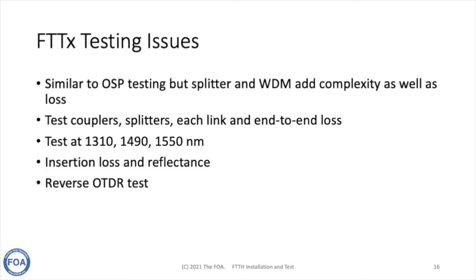The tests that will be done will be tests to measure end-to-end insertion loss during installation and before operation, with tests done at both 1310 and 1490 nanometers, and maybe at 1550 nanometers. They will require insertion loss tests and reflectance tests.